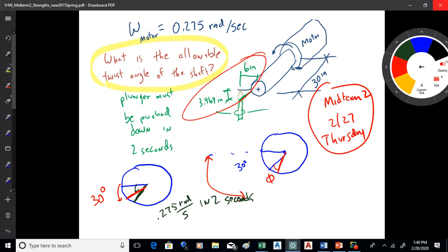So specifically, we're looking at how much the shaft is binding up. Yes, you might say that. And to make it simple, if the backside goes 32 degrees and the front side only has to go 30, you can have a little bit of twist in the shaft, because you can have a difference between the front and the back. That's basically it. I'm just trying to illustrate what that twist is in a shaft. We good with that? Okay.